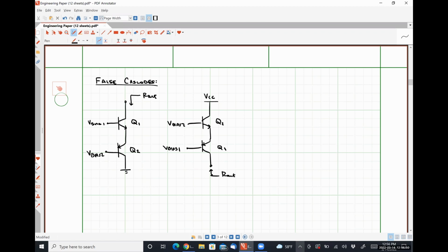All right, so these fundamentally look extraordinarily similar to what we've just done. The only real change is that for this one on the left, instead of degenerating by the same type of transistor, we've degenerated by the opposite type, okay? What does this do fundamentally? At a small signal level, what's the difference between these circuits, or between these two circuits and what we previously talked about? They're not of the same type. Right, but what small signal change occurs because of that?